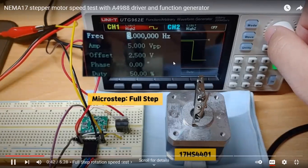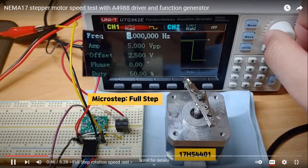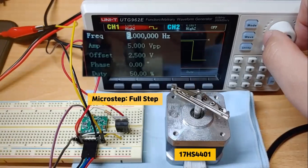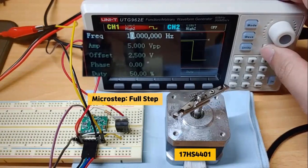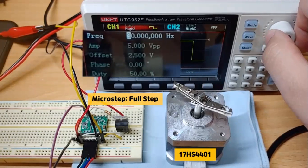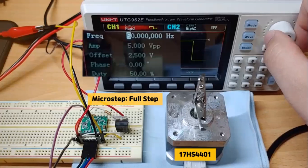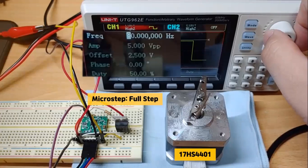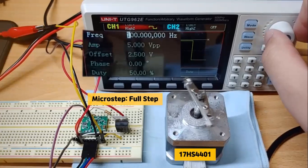When it is 3 hertz, the speed of rotation increases a bit more. At 4, the speed of rotation is increased. See the 5 value, the speed of rotation is increased. 6, 7. As the count keeps increasing, from 10 to 20, the speed almost doubles. 40 hertz, 50 hertz. So the more excitation you give, the more the speed of rotation will increase.